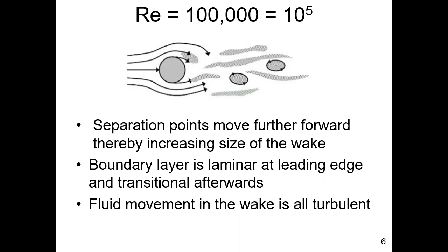And why that wake happens is, as the boundary layer starts at the very leading edge of the object, and as it moves along the object and grows, what's happening is, again, the fluid is transmitting this signal that somewhere down there is a solid surface with a velocity different than the free stream. And that signal is trying to be transmitted through the fluid object as the flow field geometry changes.